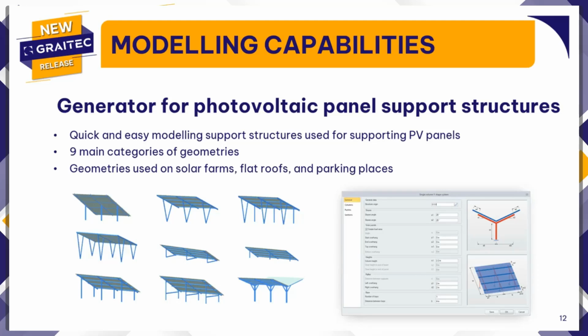We can also change other settings, like deciding if you define punctual or linear supports, and if the load area is generated. Separately for columns, rafters, purlins, and also bracing linear elements, we can assign predefined steel design settings, materials, and different sections.